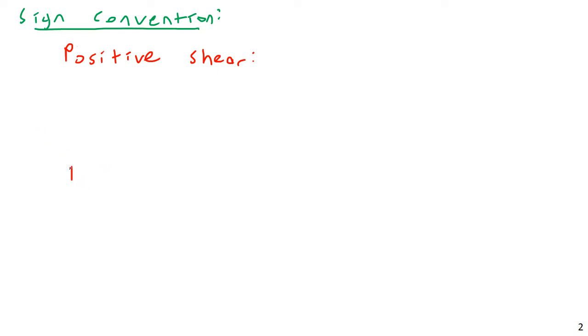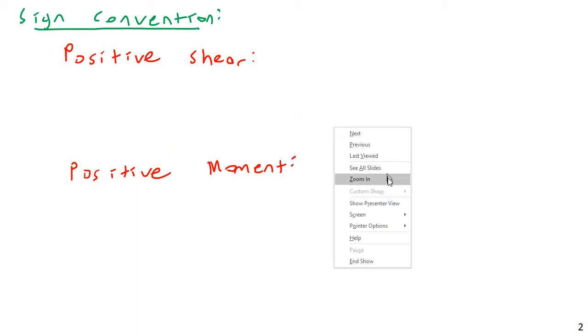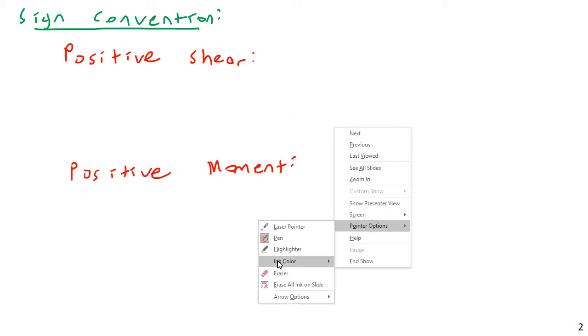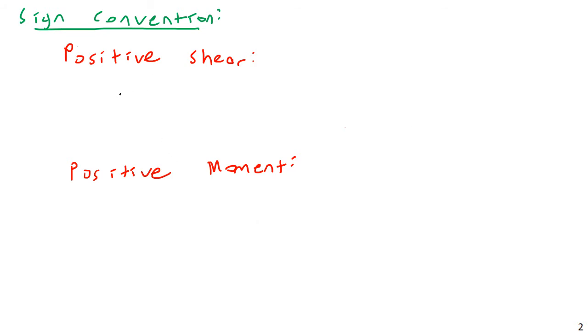But when you draw a free body diagram using method of sections in a beam, defining positive and negative shear and moment is a bit more complex. So I'm going to draw two elements, here and here. Just two elements, like a section of the beam. Imagine if I cut out a small length of the beam and looked at the forces herein.